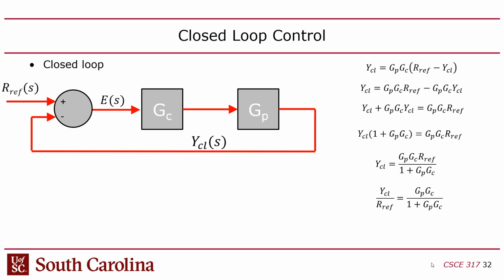Now keep in mind though that that closed loop may have more than two transfer functions in it, right? Also, this closed loop might actually be part of a bigger closed loop, right? It may be nested. You could have controllers nested inside of controllers, right? So for example, in a robot, you may have a closed loop to control one finger, which is contained inside another closed loop that controls the hand, which is inside another closed loop that controls the arm, which is inside another closed loop that controls the body, right? So all of this stuff can be very easily composed into complex systems, right? Just by applying the convolutions and the closed form formula and doing algebra to get things into the form you need.